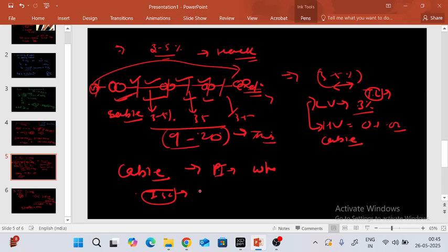When I provide the ISC value, the length of the cable or any length of circuit, we will define how many runs of the cables are required and which SQM I have to use. These things we will elaborate in a detailed Excel sheet